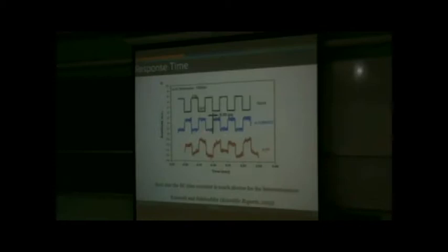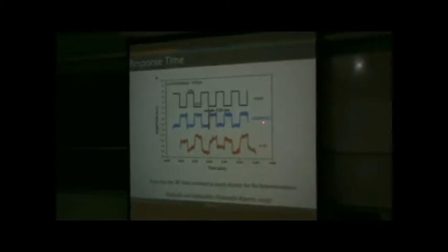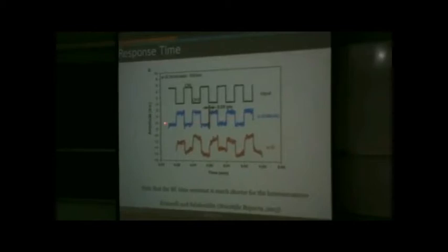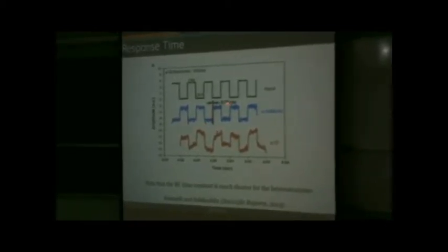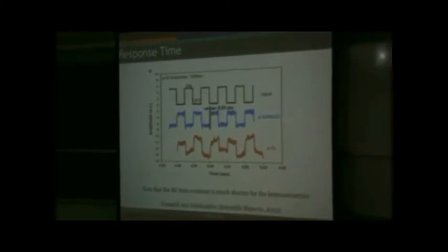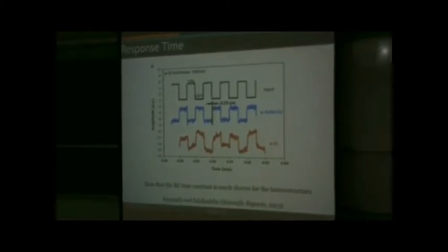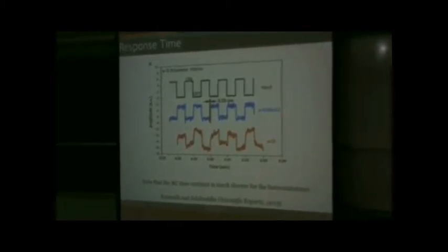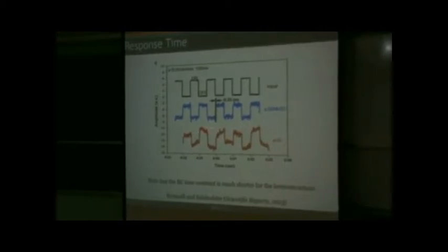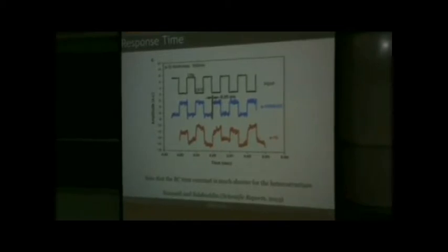If I look at the imager speed, this is the conventional amorphous silicon imager speed. This is the amorphous silicon MoS2 heterostructure photodetector, and I get a 0.25 millisecond response time, which is almost 2 orders of magnitude smaller compared to the commercial photodetector. Okay, so we were actually very happy with these results. We are not from the photodetector literature, so we did not know that it could be very important.